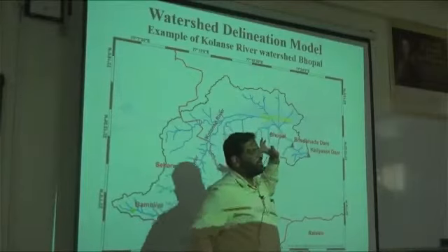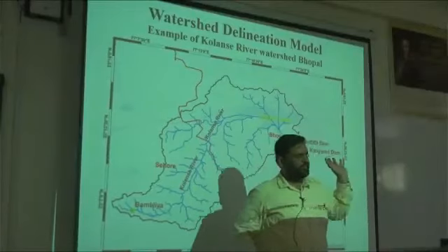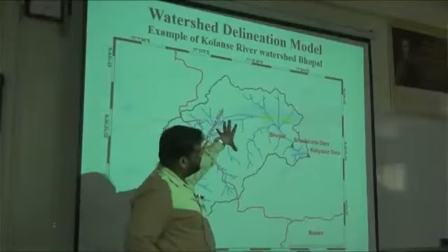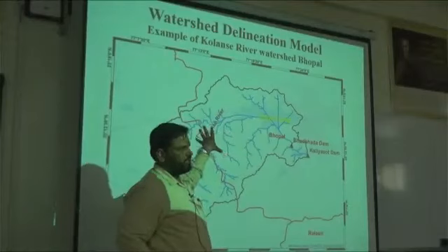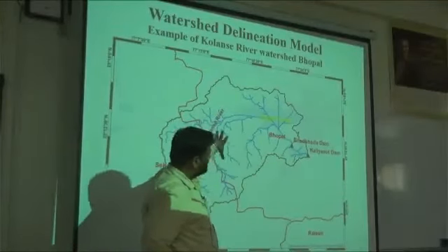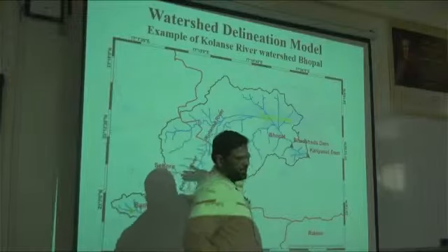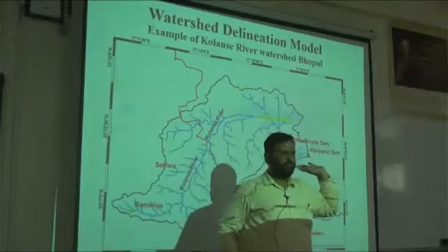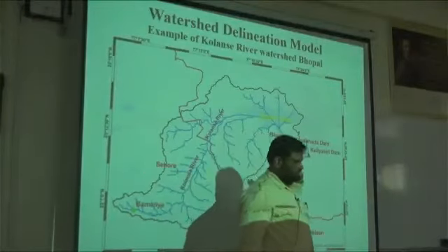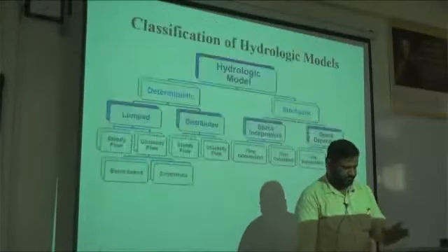With the help of some kind of GIS software, you can create these types of watersheds or stream networks. You can compute the stream orders or the complete geomorphology: what is the area of this particular catchment, the stream orders, stream length, how the tributaries are contributing to that. If you have rainfall and land use and all types of other data, you can use that data in any models, not only in SWAT, or you can generate the statistics.